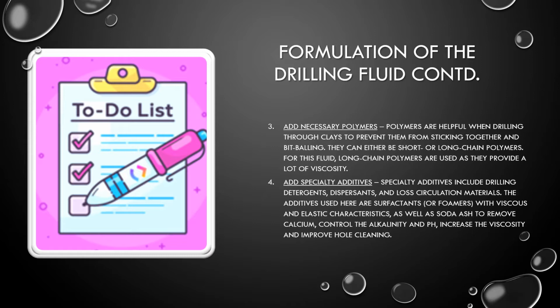Step 3 is to add the necessary polymers. Polymers are helpful when drilling through clays to prevent the clays from sticking together and bit balling. They can either be short or long chain polymers. For this fluid, long chain polymers are used as they provide a lot of viscosity.